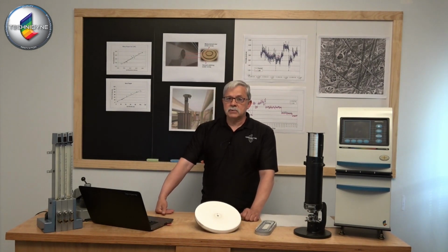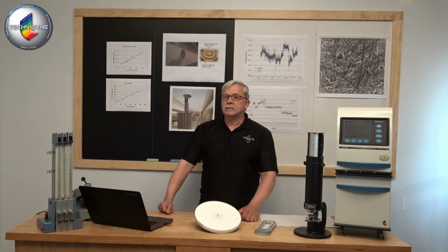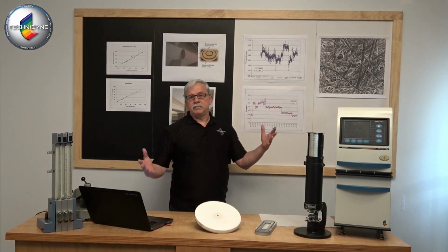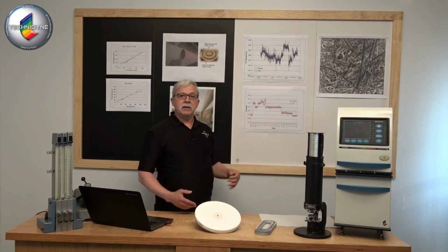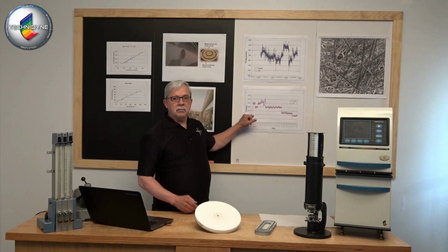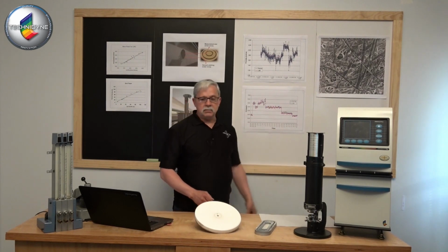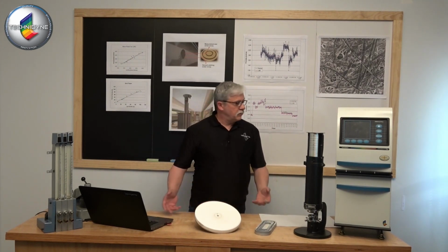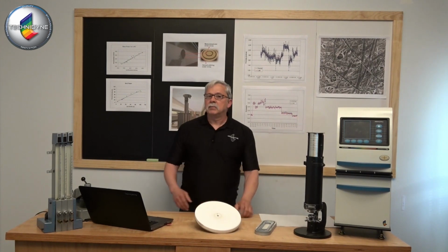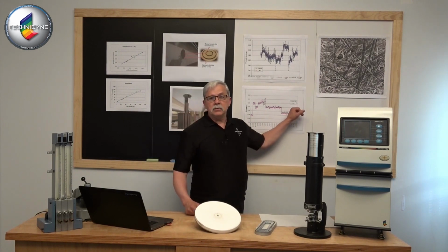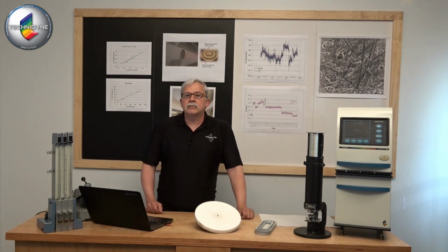Reduced grade change times. There's been excellent response from customers who've taken 15% shorter grade changes. The time to make a grade change starts out with a certain level of porosity measured, going through a grade change, and in this particular case, maybe in less than 15 minutes, they've got the grade running back where it originally was. Or it could be at a new target.